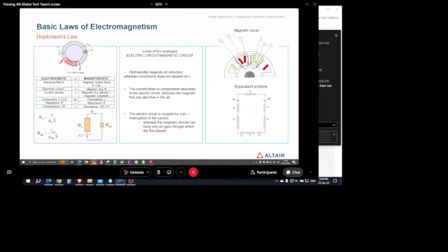So if we say that there is a reluctance for the magnetic circuit, there is a reluctance for the air gap. The reluctance of the air gap is the length of the air gap divided by mu0 multiplied by S. Why mu0 only? Because the relative permeability of air, of the vacuum, is equal to 1. And then here we have the iron, the mean length of the iron divided by mu iron multiplied by the same section.